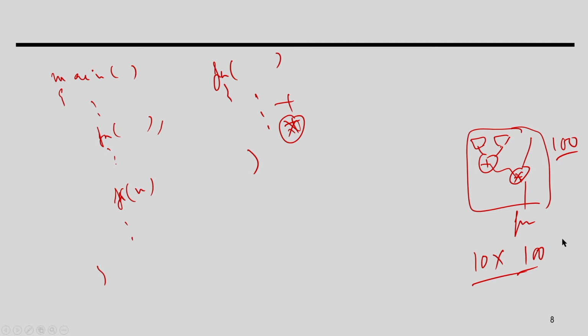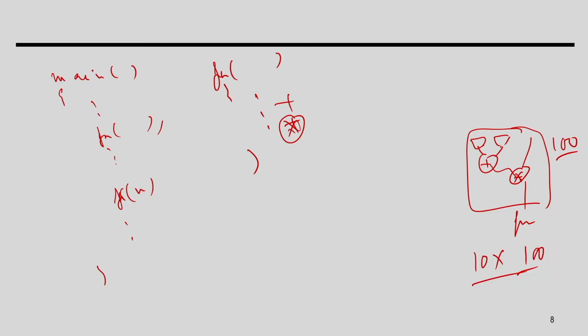What I am trying to say is, once I map these functions into hardware, my primary objective will be to create one copy of the hardware corresponding to a function. But depending on how the schedule has been generated, sometimes it may not be possible. If there are two calls with no dependency between these two functions, the schedule might run them in parallel. It can happen, because suppose one is taking arguments a and b and the other is taking arguments x and y, and there is no relation between these two. So, these two functions become independent of each other.